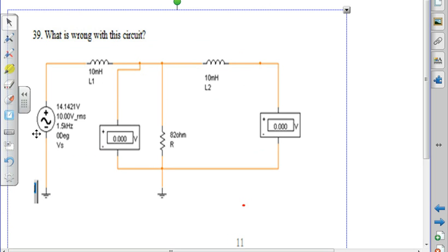Okay, I've got some 1K and 100 milli. These guys are not all that big of a resistance. But no current, no voltage is getting over to the other half. So there could be multiple things wrong with this guy. Okay, it could be that both the voltmeters are DC. Okay, you could come to that conclusion, or you could come to the conclusion that L1 is open.